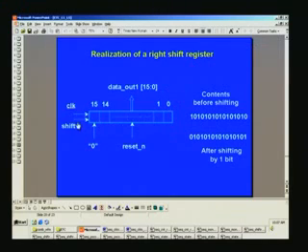There's a clock input and a shift here, and vacated bits are filled by 0, and there's also a power-on reset here. We start with the contents 1010 and then right shift by 1 bit, because it's a right shift by 1 bit. So you should get this. So let us look at the waveform.